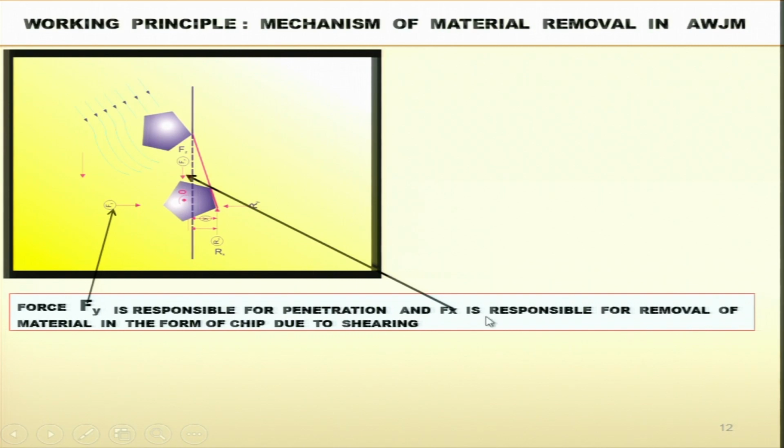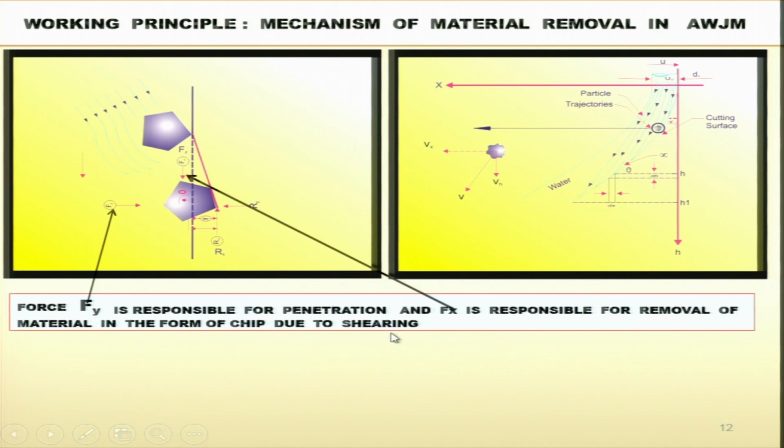And then there is the Fx. This is the Fx force, as you can see here, and it is moving this abrasive particle after penetration in this particular direction, so that it will remove the material in the form of micro or macro chip, responsible for removal of material in the form of chip due to shearing action.